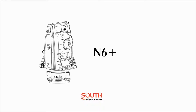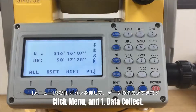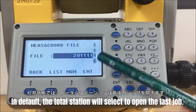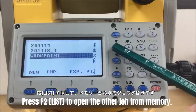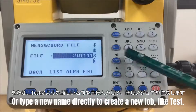In this episode, we will introduce how to create a new job and the other operations. Click Menu, and the first item, Data Collect. By default, the total station will select to open the last job. Press F2 List to open another job from memory. Or type a new name directly to create a new job, like test.